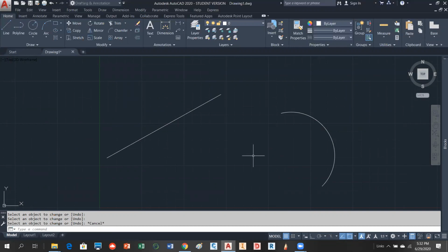So if we hit the escape key, go back into the lengthen command. Let's change our delta value to a negative. So if we say a -1, for instance, now come up here, it's trimming, it's trimming, it's trimming, trimming, okay? So that's also pretty neat the way that's working, just chopping off little pieces, okay? So either positive or negative values of delta, angle, or delta length, okay? Is that working? Yep. Okay, so let's check the next option on lengthen.